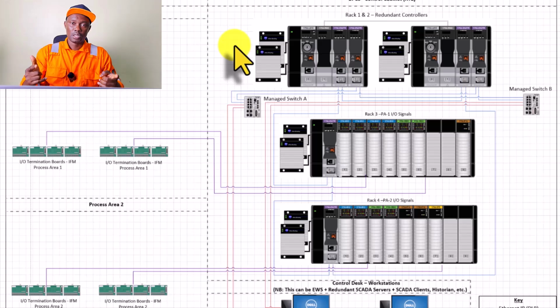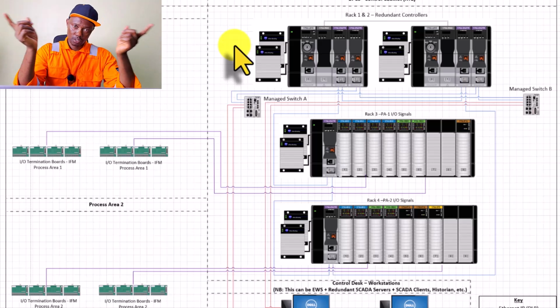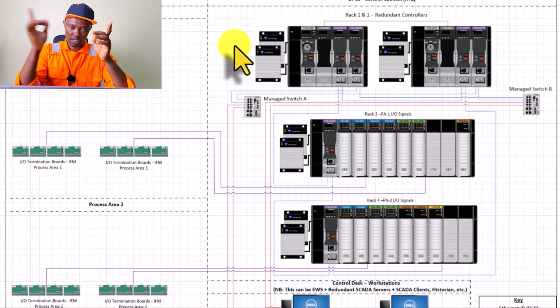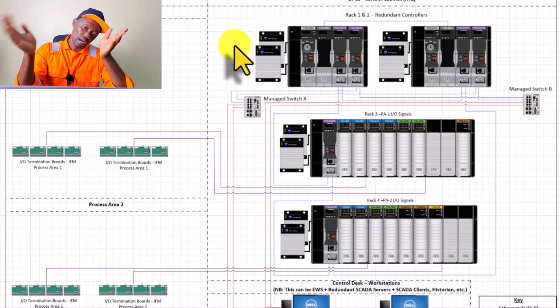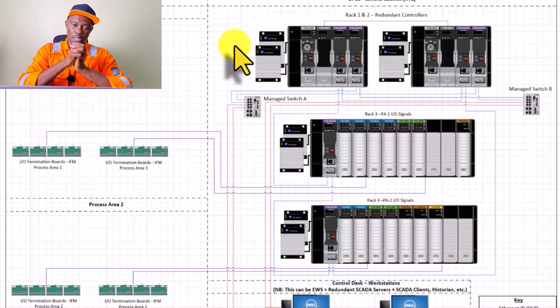When there's a failure or something happens and the system needs to switch over from primary to the secondary, the secondary takes over the same IP address of the primary. When you put the system in run mode in the first place, the primary takes .30, then the one you made available, the secondary takes it. But during the switching, the secondary now takes the primary IP, while the one after it you made available moves to the previous primary. So that's how it works, okay?